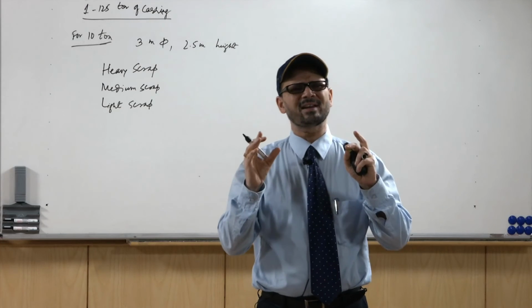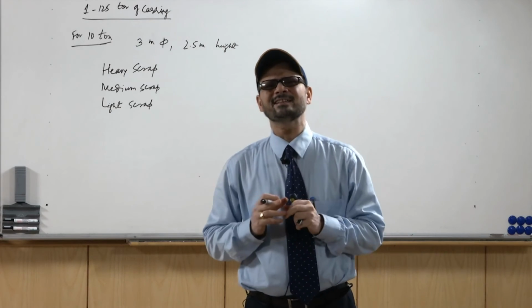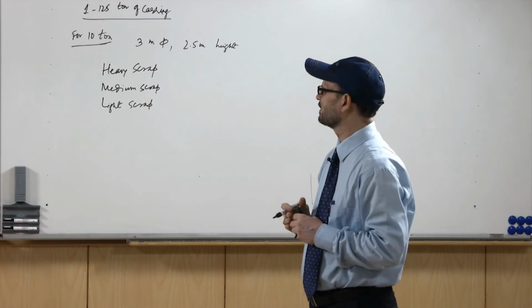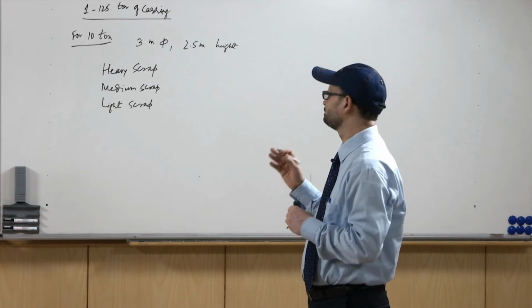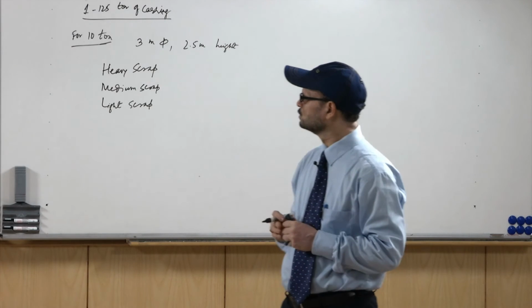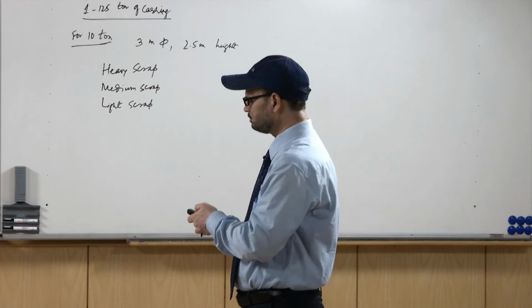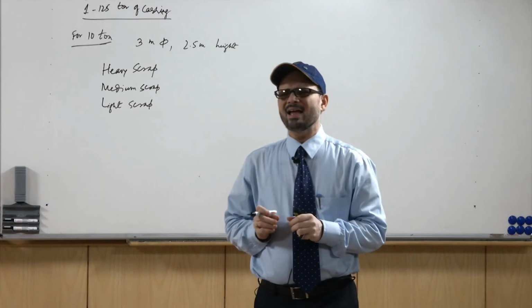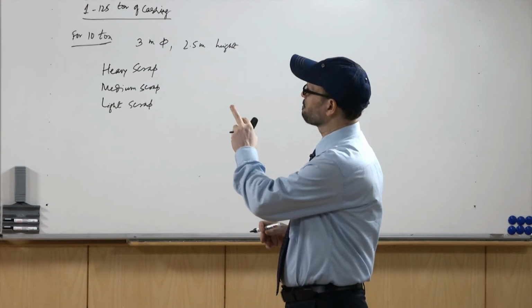In the induction furnace, the frequency is there; high frequency, medium and low frequency types of induction furnaces are used, depending upon the frequency of the current which you use. It also has a monolithic type of lining structure, and it is a very quiet operation.